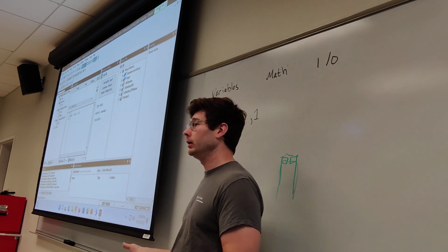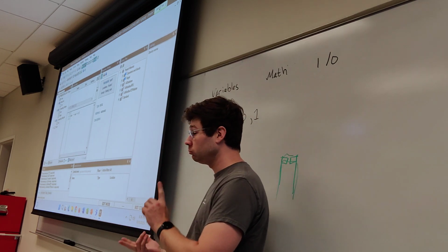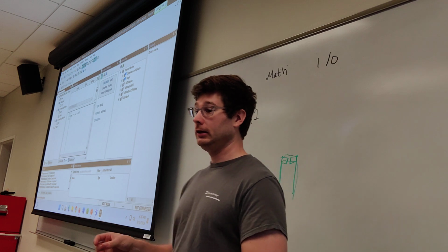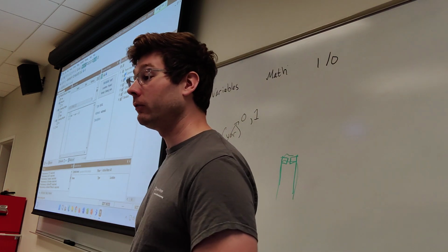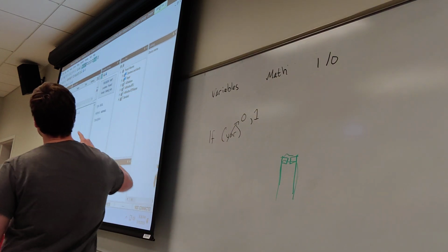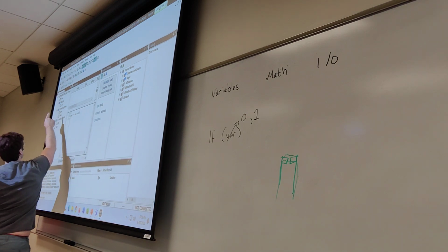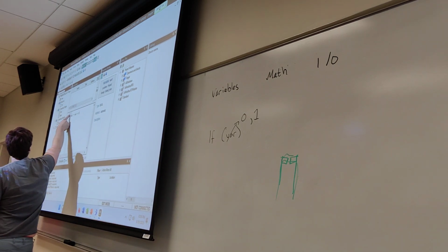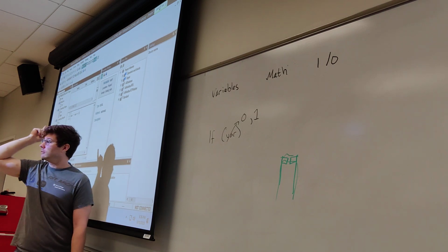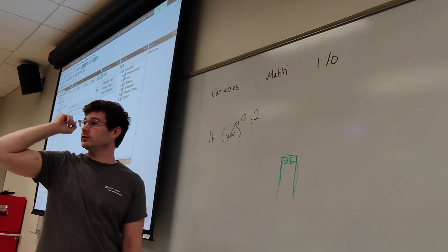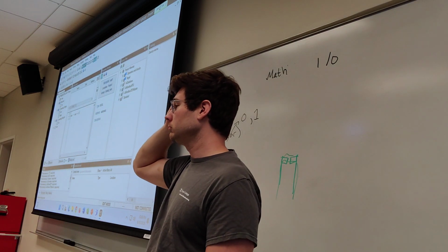Why do people still use PLCs? It's because they're easy, they're really reliable, they're easy to maintain, and they have awesome debug modes like this. If you click this button that my mouse is hovering over here, this is called live debug mode. You'll see what pops up right next to the variable is a live preview of the current status of that variable.